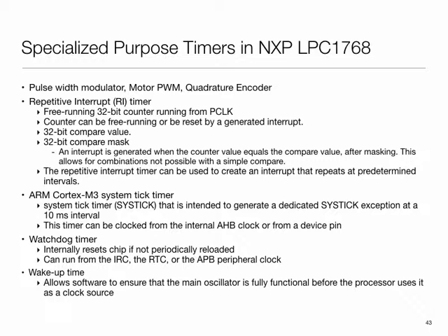Yeah, okay. So basically, I want to guard against the process software hanging. The idea is that if the software hangs, then it will not reach the part of code which disables the timer. If the software is working correctly, it will start the watchdog timer, and before it causes the reset, the timer would be disabled. So in correctly functioning software, if it hangs or takes longer, we will not reach that stage, and then the reset would kick in.